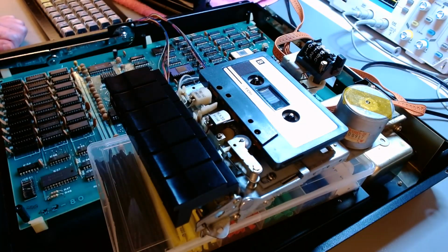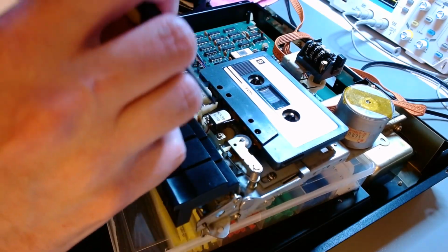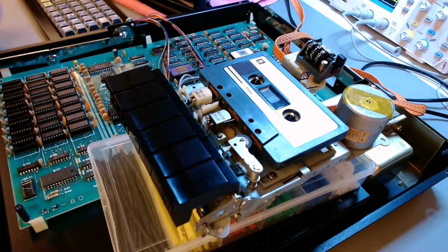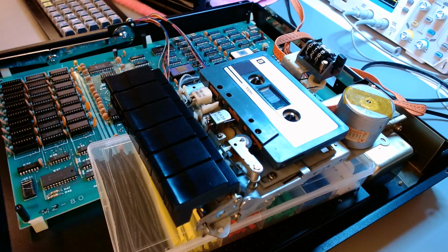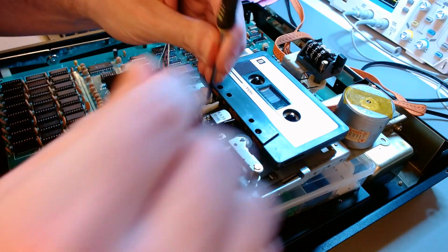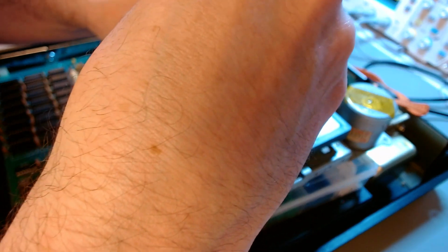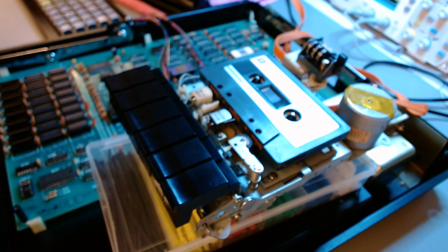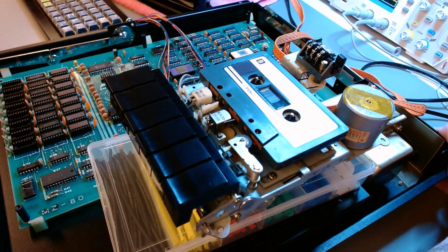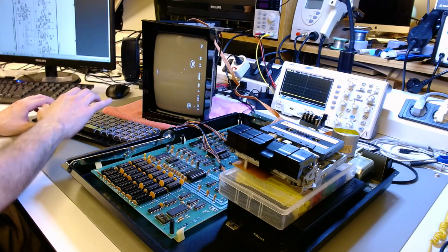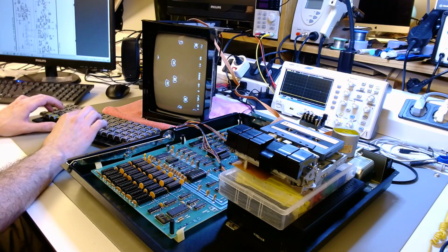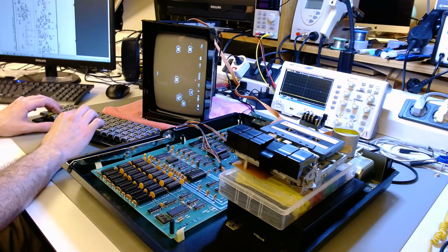So I decided to adjust the azimuth screw in the cassette player. Usually you have to hook an oscilloscope to the collector of a transistor deep inside the player. You have to disassemble it again. That's the only way to do it systematically and reliably. But right now, as you would see if my big hand were not in the way, I'm just adjusting that by eye, just trying to load a program again. And sure enough, it loads. It does load. And there is me playing that game, but not always right.